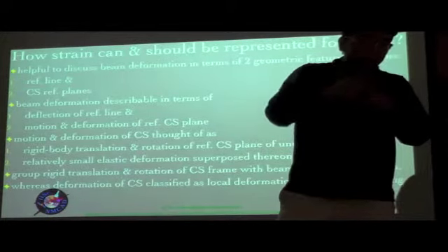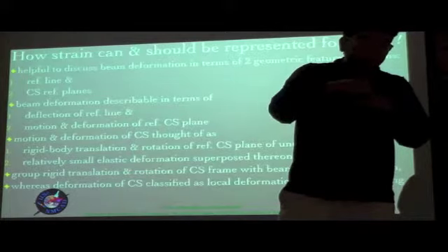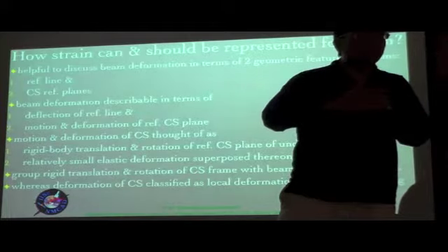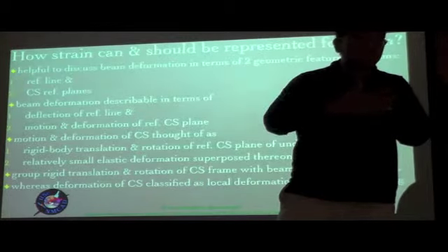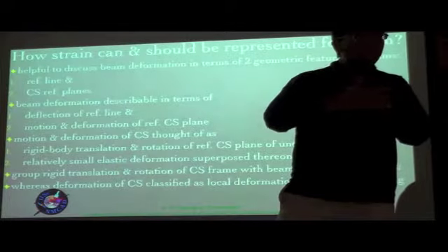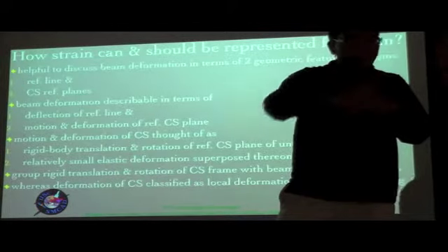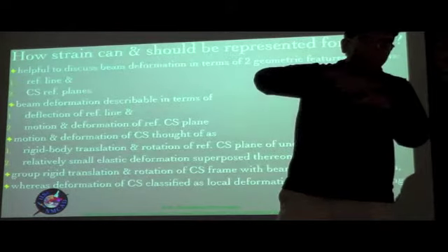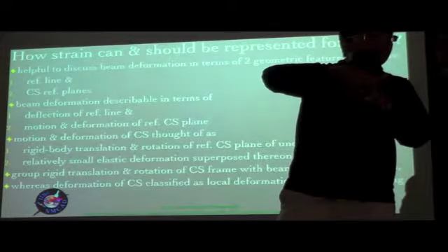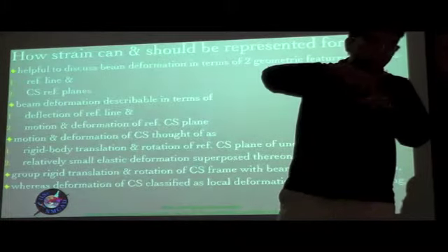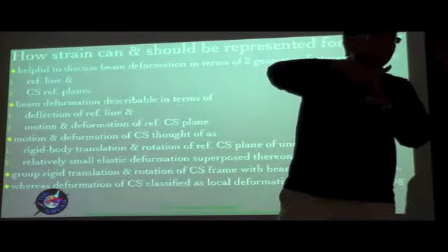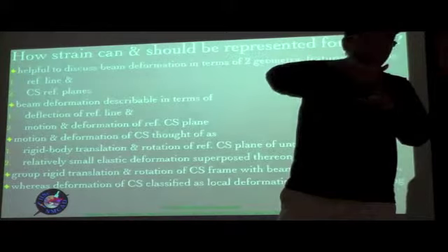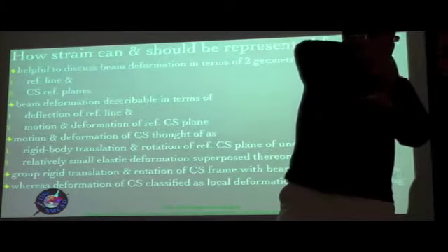Okay, so now let us say we are talking about the warping W1. Okay, so W1 is basically this cross section coming out. Okay, so it is basically becoming like this. Okay, and it is over and above the average displacements that have already happened for the cross section. Now at a particular location, that is a line element, can become something like this. Okay, so now that can be thought of as basically an average translation of that line element and an average rotation basically in this direction as well as in this direction, right?